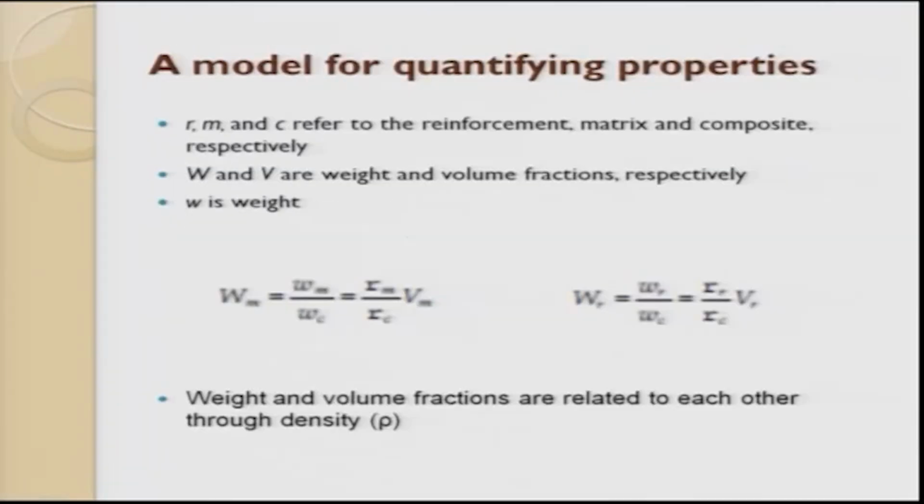Now, let us try to understand the volume fraction and weight fraction. They are generally talked about in composites because they play an important role in deciding the amount of reinforcement added. Generally, a manufacturing engineer talks about weight fraction. A theoretician, doing a first principle theoretical calculation, always talks in terms of volume fraction. These two are interrelated by density. Density is nothing but mass by volume.